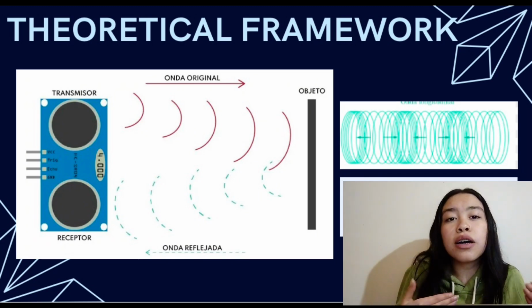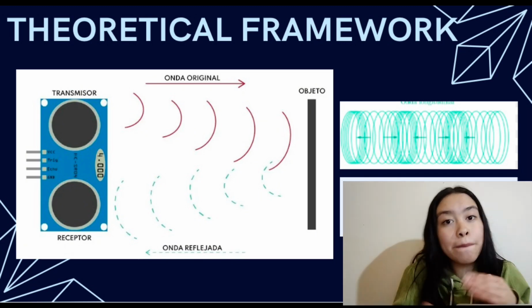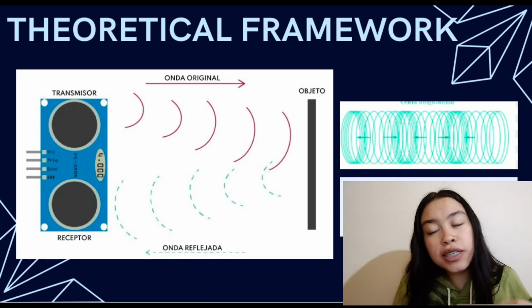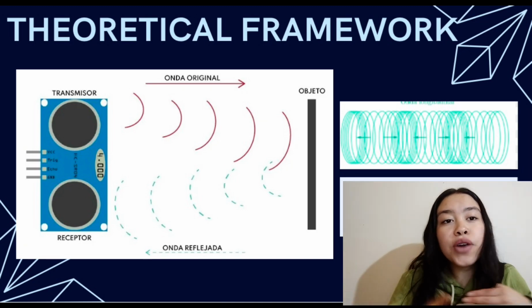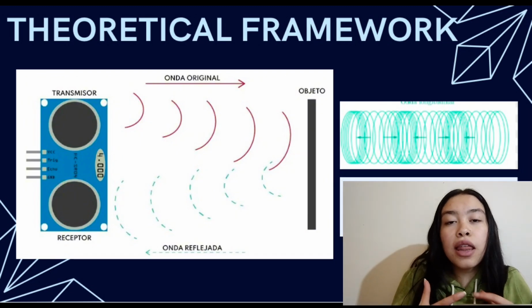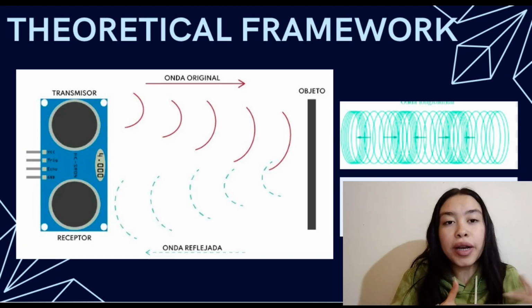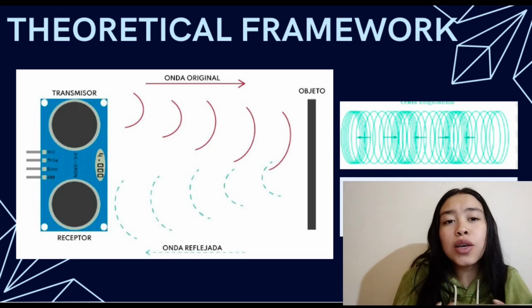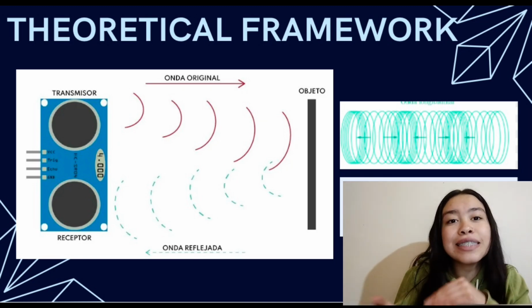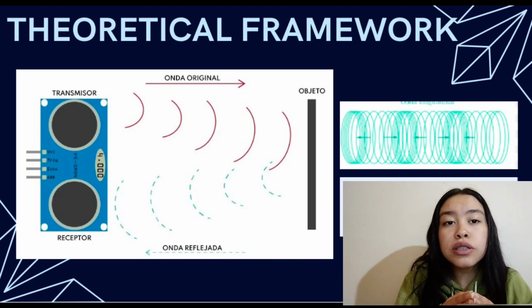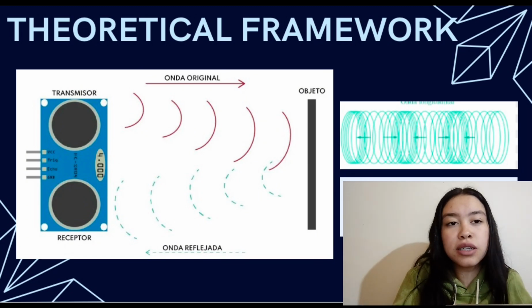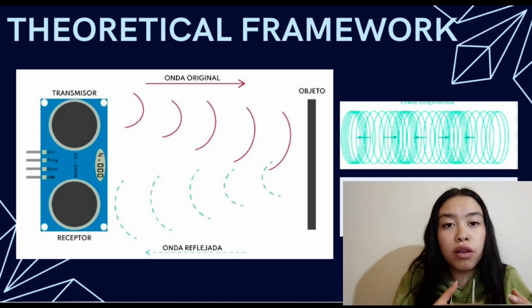Ultrasonic waves are a propagation of vibrations which have a very small wavelength, which often affects the different phenomena associated with wave propagation. Ultrasonic wave propagation in an elastic material is due to the successive displacement of its particles.